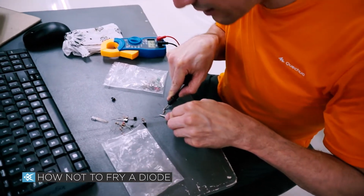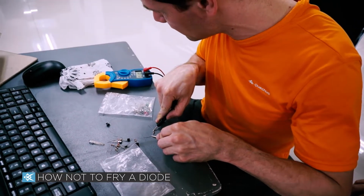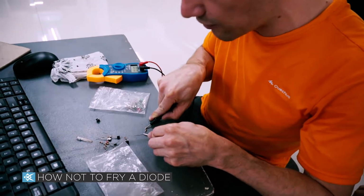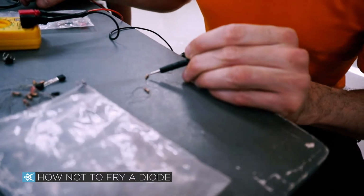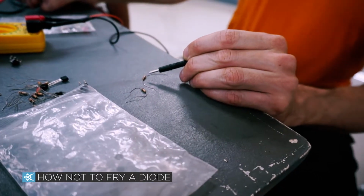So what are we doing right now? We're looking at the resistance of a particular resistor. So that's 1000 ohm. Brown means 1, black means 0, and red means a multiplier of 1K.